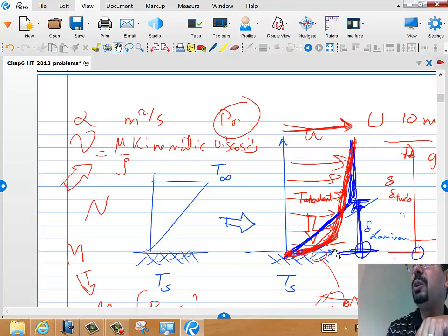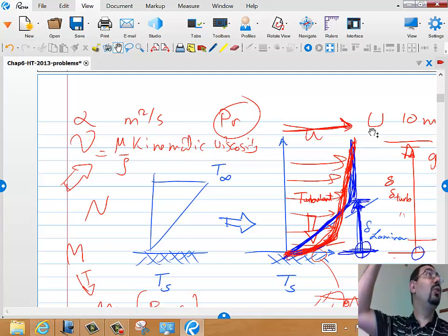So it brings the fluid velocity all the way down to the wall, but it also takes the wall effect all the way up, meaning more and more layers are noticing that there is a wall down there and their velocity is affected. So the idea is that turbulence makes the fluid very well connected. The top hears about the bottom, the bottom hears about the top. So you get very high velocity near the wall and you get the wall effect all the way up.